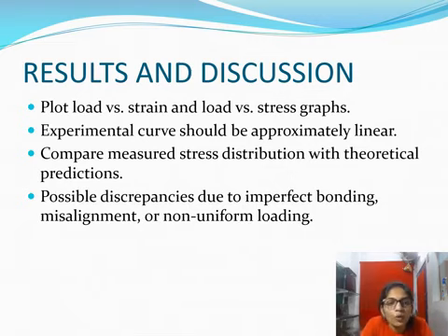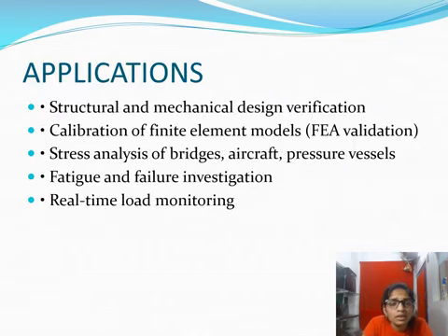Result and discussion. Plot load versus strain and load versus stress graphs. Experimental curves should be approximately linear. Compare the measured stress distribution with the theoretical prediction. Possible discrepancies are due to imperfect bonding, misalignment, or non-uniform loading.